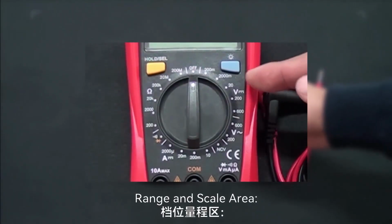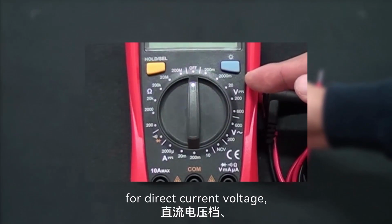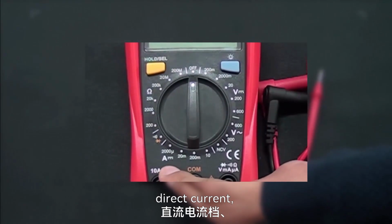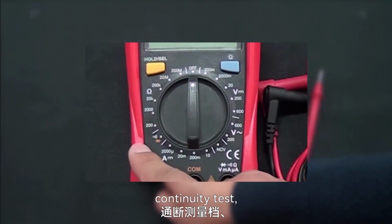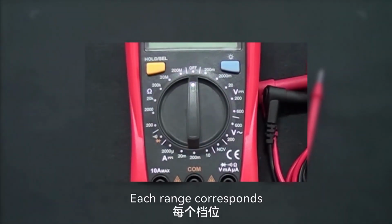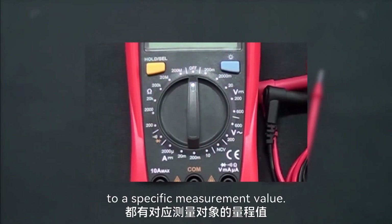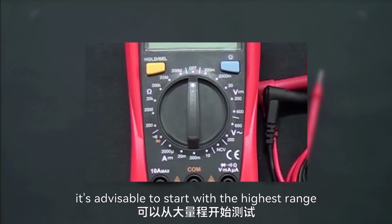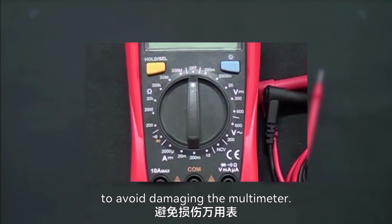Range and scale area. This area includes settings for direct current voltage, alternating current voltage, direct current, continuity test, and resistance. Each range corresponds to a specific measurement value. If the magnitude of the measurement is unknown, it's advisable to start with the highest range to avoid damaging the multimeter.